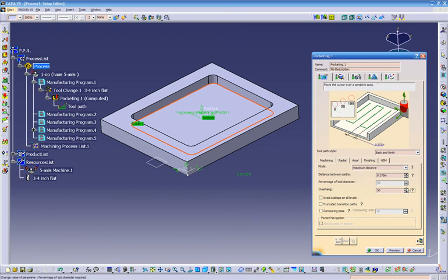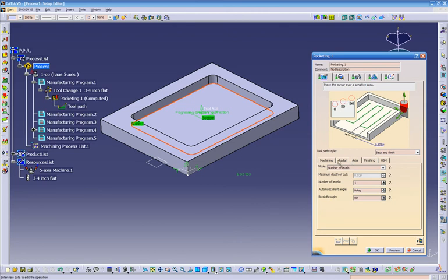They show you right here the difference. But I like ratio the best, 50% of the tool. Then we have radial was going sideways, as you see. Axial goes up and down. So it's asking us how many depth of cuts do we want. So just click on this and it will tell you 1, 2, 3, 4.